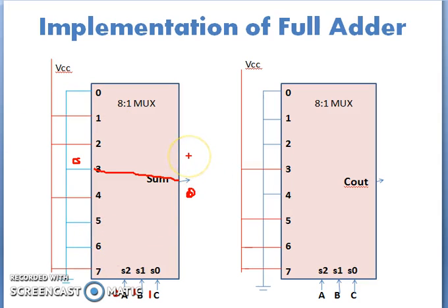Okay. Likewise, we have to go for all respective connections. Where we want some value 1, if I consider the 0, 0 and 1 input, so 0 plus 0 plus 1, output sum will be 1, and according to multiplexer behavior, 0, 0, 1 means input number 1, whatever you apply over here, is getting transferred over here. As we want 1 at this combination, we have to apply over here logic 1.